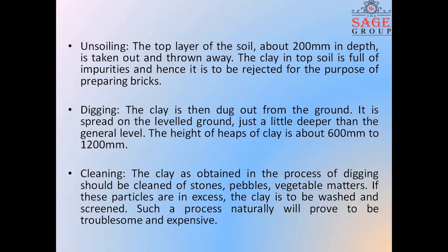Then after the unsoiling, the digging process occurs, in which the clay is dug out from the ground and it is spreaded on the level ground so that the excess moisture can be removed easily in the atmosphere. And the height of the heap of the clay is about 600 mm to 1200 mm.